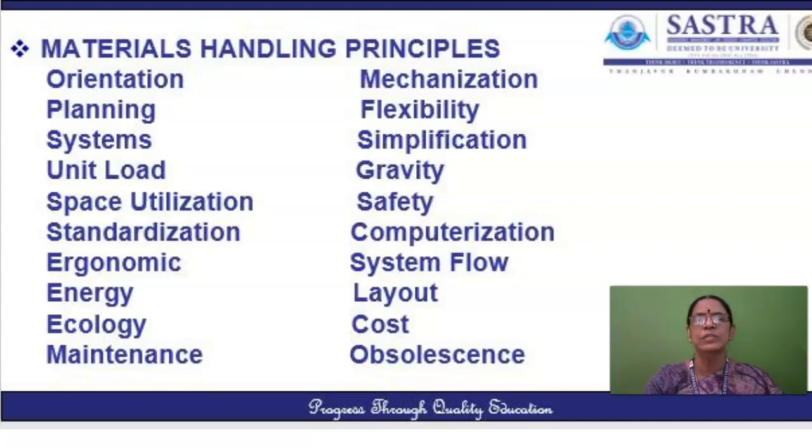Next is the space utilization principle. This principle insists on the effective and efficient usage of the available space in an organization. Space in material handling is three-dimensional and therefore counted as a cubic space. In work areas, clutter, unorganized spaces and blocked aisles should be eliminated. In storage areas, the objective of maximizing the storage density must be balanced against accessibility and selectivity. While transporting the loads within the facility, the use of overhead space should be considered as an option.